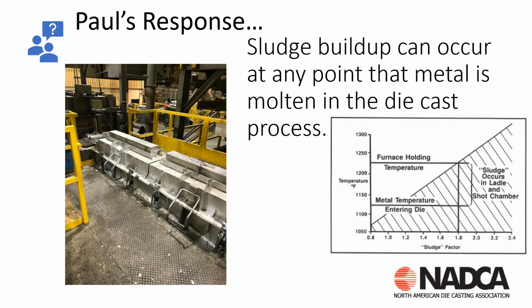When sludge starts to form, if it is not agitated, if it is not solidifying rapidly, like in the die casting, then the crystals are going to grow large. So we're going to have large crystals in our holding pots, in our launder sections, in our breakdown furnaces. And those large crystals are forming because they have plenty of time to grow.